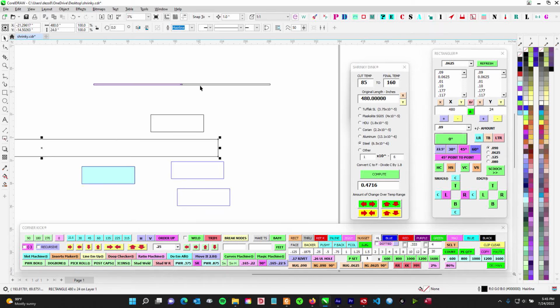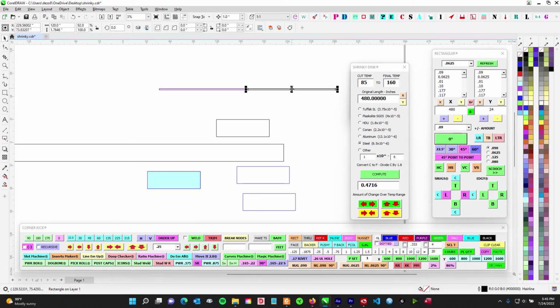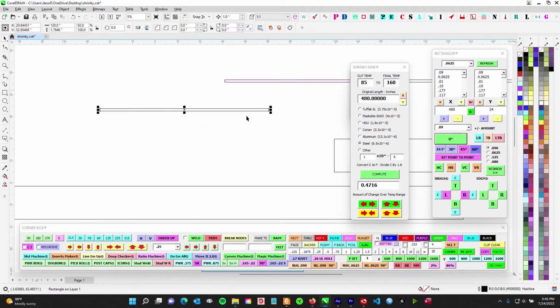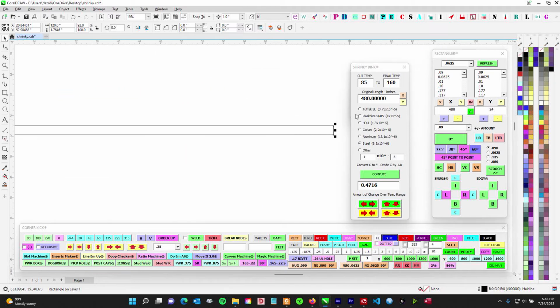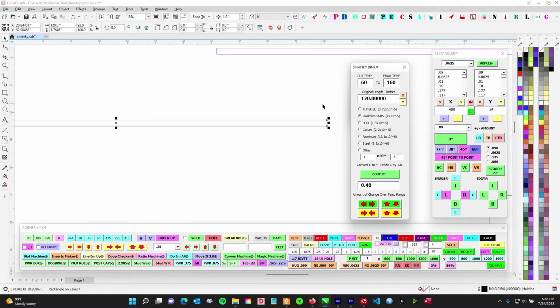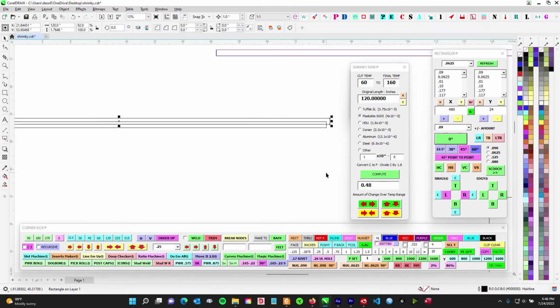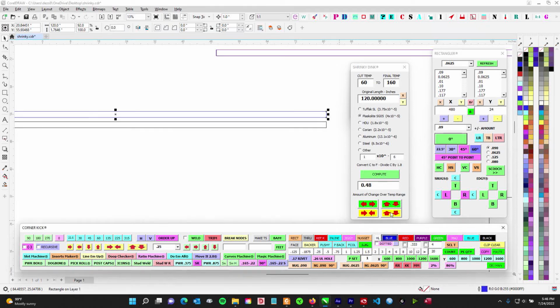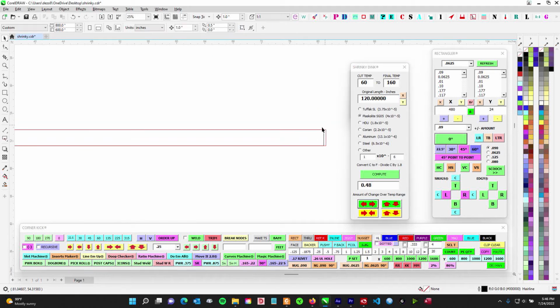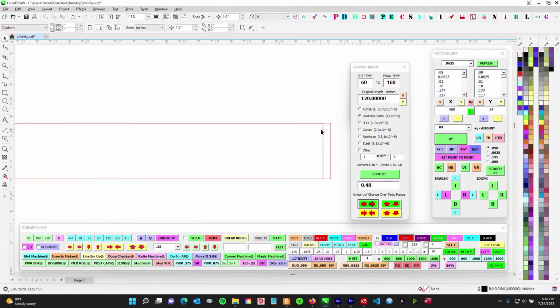And that's not to say, I forgot that if you change the dimension or you change the temperature of when this is cut. So let's say you have this same bar at 120 inches, but you cut it when it's really cold. So let's say in your shop it's 60 degrees, and then you go ahead and make that out of acrylic. Look at that. I mean, you have 0.48 of difference in how long this thing is going to grow. So I'm going to go ahead and add that. And just for ha-has, look at that. Look at how much that's going to be very angry.